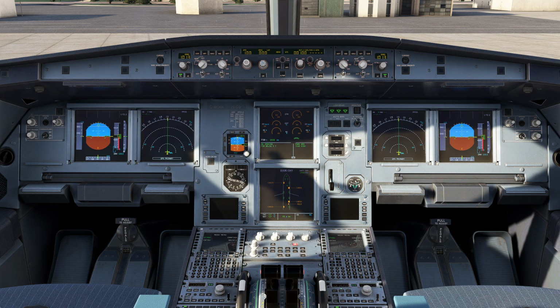Other computers which help the EIS on Airbus A320 families is the System Data Acquisition Concentrator, or SDAC. We have two identical SDACs that acquire data, then generate signals. Some of these signals go to the three DMCs, which we talked about already in the previous section, which use them to generate the display of system pages and also engine parameters.